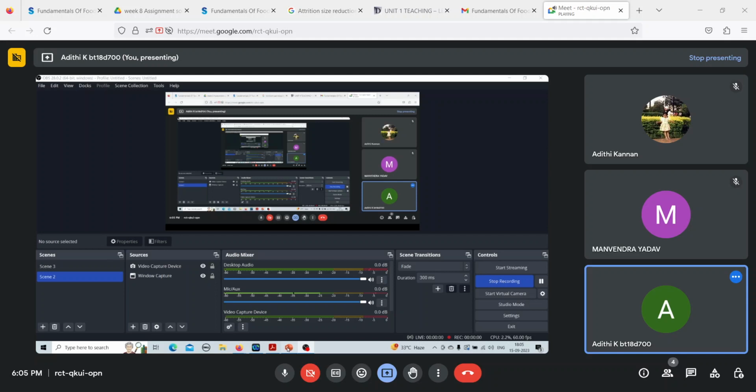So going to question 18. The work index of a material is 5.85. If 80% of the feed and 80% of the product can pass through the sieve opening of 3500 micrometer and 450 micrometer respectively, the power consumed to crush 120 kg per hour of sorghum is dash.